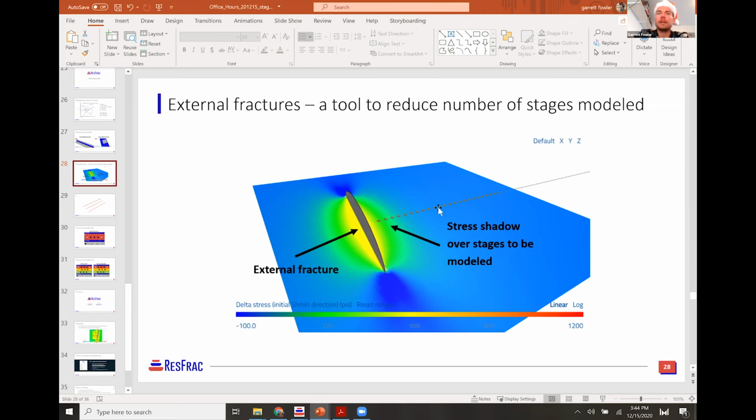And run a simulation. And if my fracture dimensions in my actual simulation end up being a little bit different, I may adjust my external fracture just slightly to match the average fracture shape of those created in the actual stage that I'm simulating. And I'm going to assign 1 per well, and they may overlap.